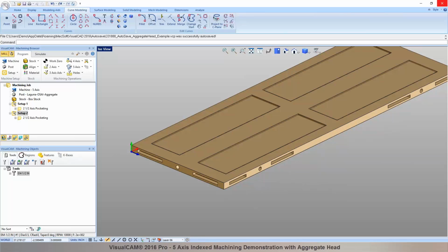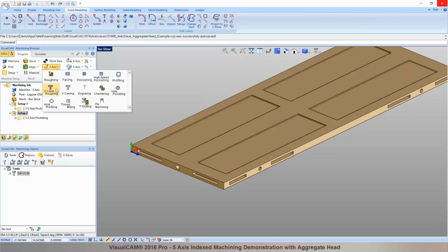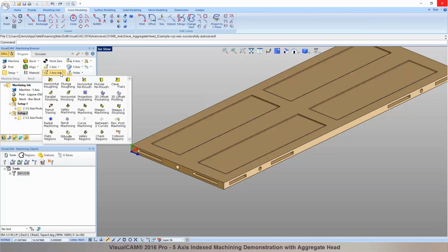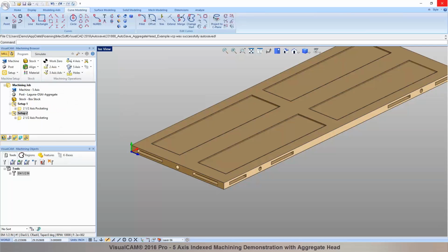And so you're really just treating it, so you still have your entire library of 2 or 3-axis moves or operations that you can run. Absolutely. You can apply all of your 2-axis methods and your 3-axis methods when you're programming indexed 5-axis or positional 5-axis. Gotcha. That's awesome. Okay, excellent.